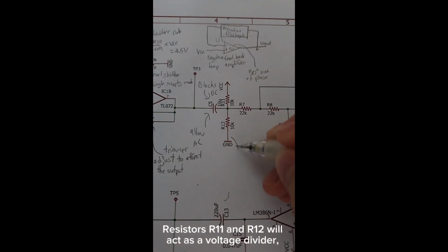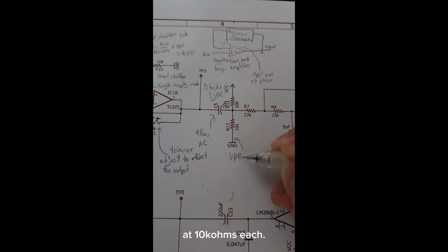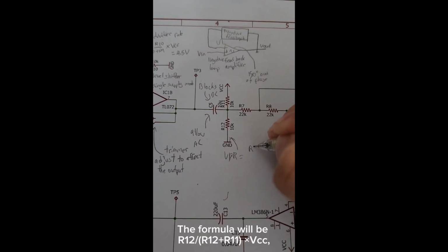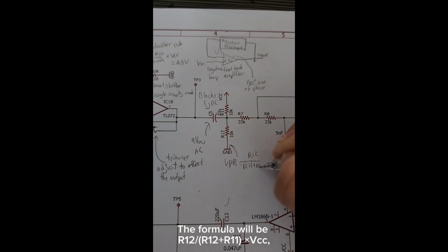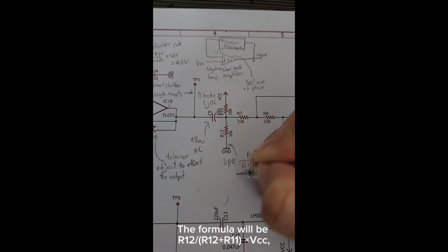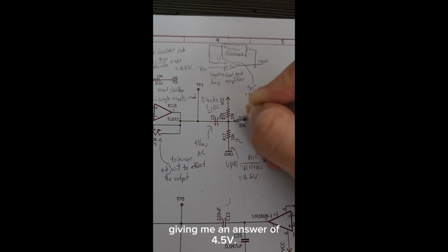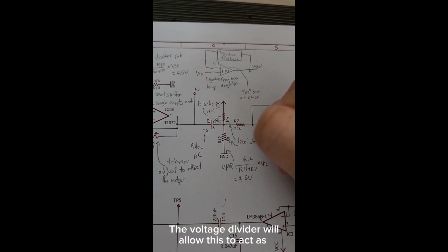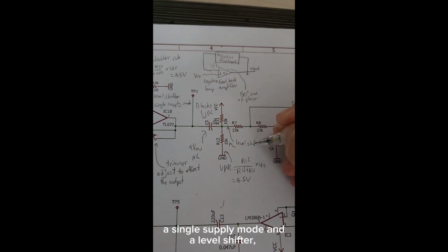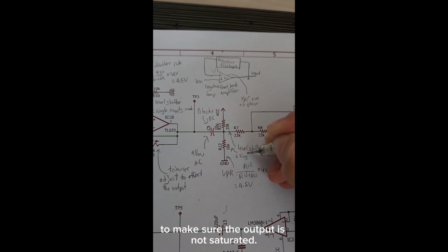Resistors R11 and R12 will act as a voltage divider at 10k ohms each. The formula will be R12 over R12 plus R11 multiplied by VCC. VCC will be supplied 9 volts, giving me an answer of 4.5 volts. The voltage divider will allow this to act as a single supply mode and a level shifter to make sure the output is not saturated.